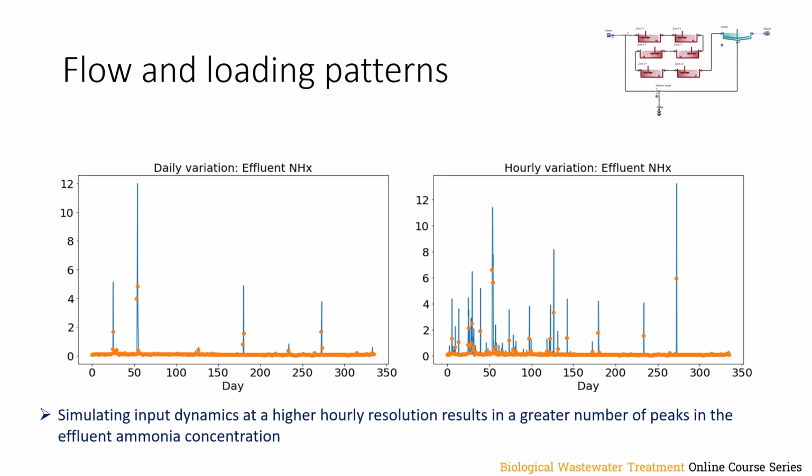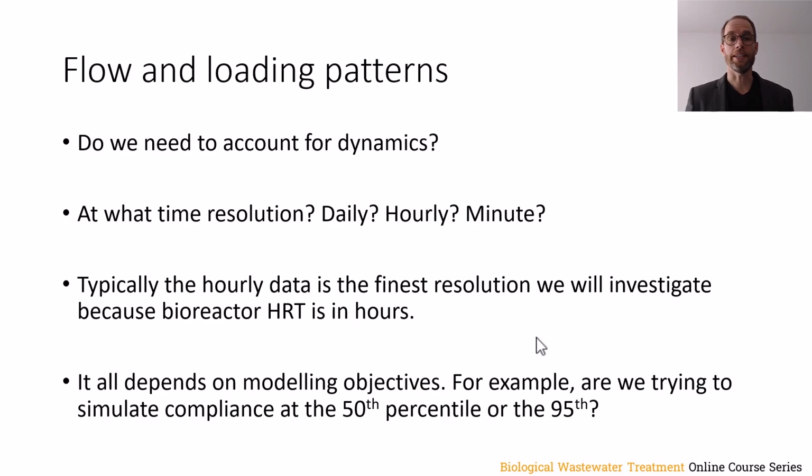But when we simulate the change in influent loading on an hourly basis, we simulate those breakthrough peaks a lot more frequently. So the higher the resolution, typically the greater the number of peaks. So do we need to account for dynamics? And at what time resolution? Should we look at it on a daily basis, on an hourly basis, or even minute to minute? Well, typically, hourly data is the finest resolution we will investigate because bioreactor HRT is in hours.